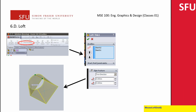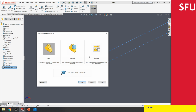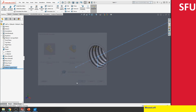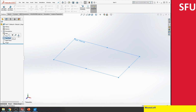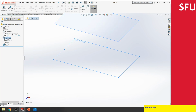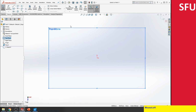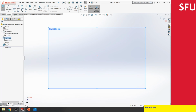If you switch back to my SolidWorks, let's create a new drawing. Control N. Let's do the same thing. We need two planes. Maybe create one more plane parallel to the top plane, maybe 100 millimeters sounds good enough. On the top plane, I'm going to create a rectangular sketch, maybe a center rectangle.